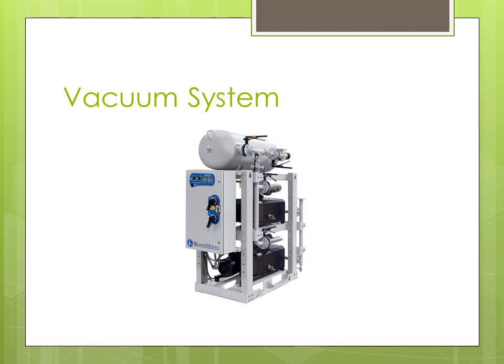Something else I want to mention here is that N+1 design. N+1, which is really a requirement in healthcare, means that you have the ability to have at least one more unit or a backup unit to what's needed. So think of N as being needed, and the 1 is extra. And really, N+1 can either be a second system that sits there passively waiting to be used in case something fails,